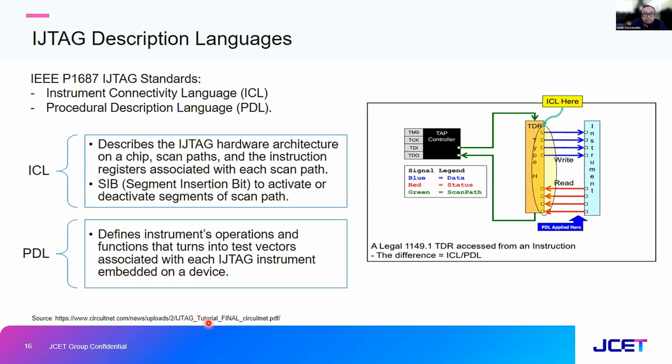And this is one of the advanced offerings, IJTAG, where you have the option of doing instrument connectivity with their language called ICL, and also the procedural description language, PDL. These are the more enhanced or advanced options or features in the EDA platform.